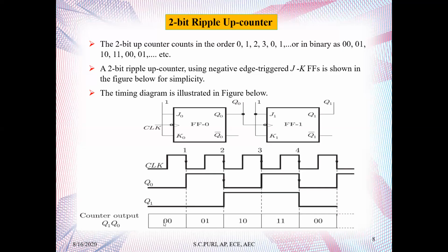And also you can see here, it is Q1 Q0. So Q1 Q0 is 00, then Q1 Q0 is 01. So you can see it is changing state, but this Q1 is not changing any state as such. And in this way, at every stage, it will count 00, 01, 10, 11. So that means it will be a 2-bit operation.